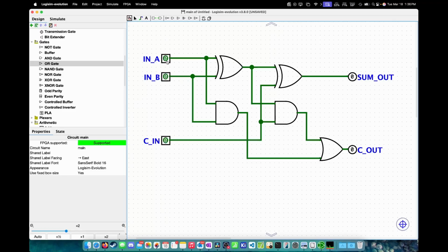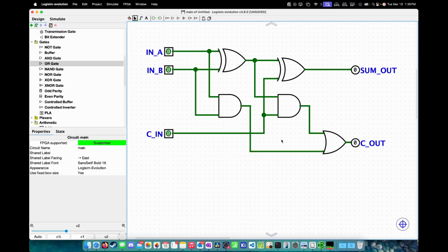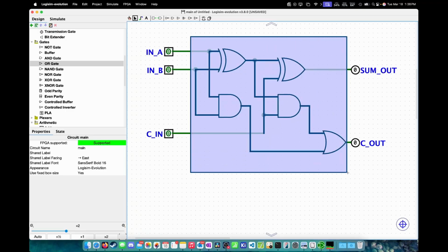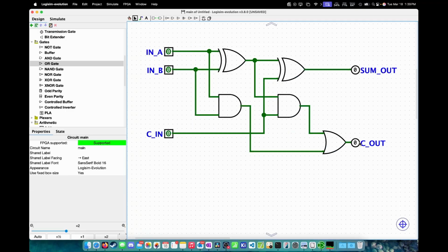So for example, this would be the equivalent of 0 plus 0 plus 0. We have the output of 0. If we have 0 plus 1 and then the carry flag is 1, it's treated as a simple addition between these three numbers. But the purpose of carry in is to interface with a carry out. If you want to add larger numbers together, all you have to do is duplicate all this in here, and then attach the carry out from here to the carry in of the one you just duplicated.